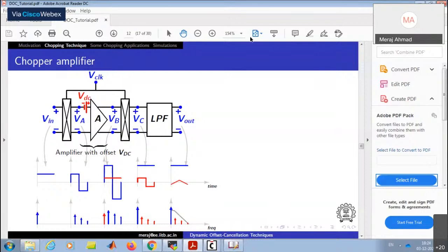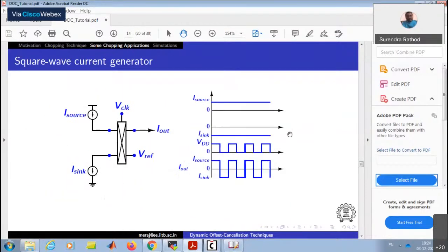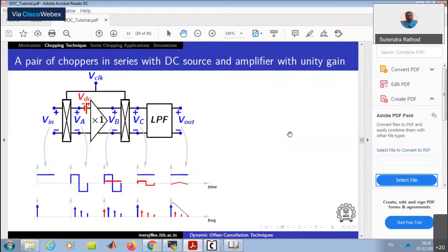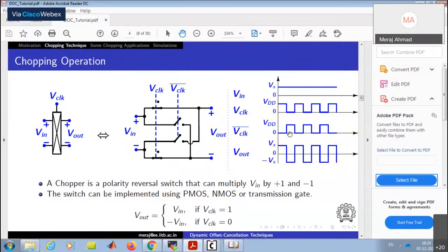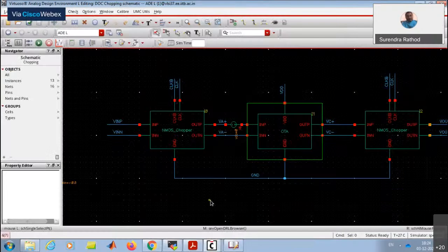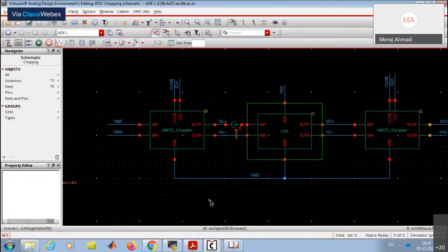So, any questions? But these transistors are kind of digital circuits, say pass transistor logic, connected in series. Yes, channel charges and this clock are directly coupled to your other terminals like source and drain. Yes, those effects will be considered. Clock feedthrough and charge injection are there. These issues are there in all choppers. So that adds to an error.